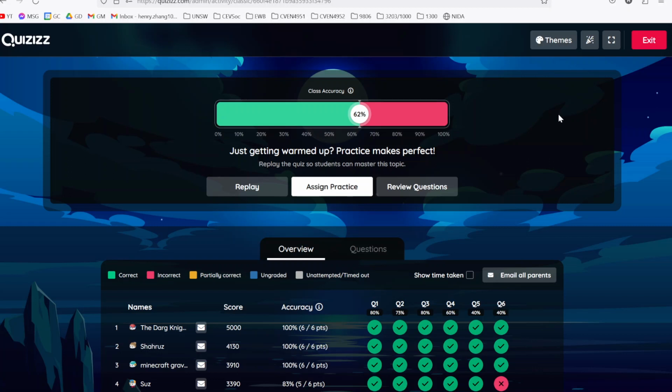But the idea is with those formulas, they just care about the average settlement, so they kind of pretend for that. So basically, the sides here will settle more than the middle, or the other way around, I can't remember. But the S average is just the average settlement of the entire footing will be that value. That's it.